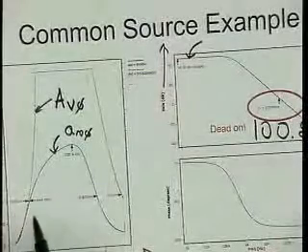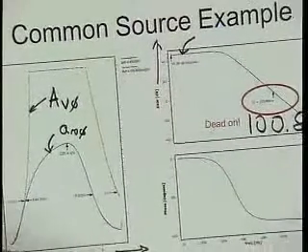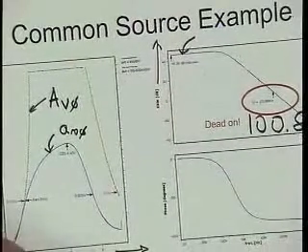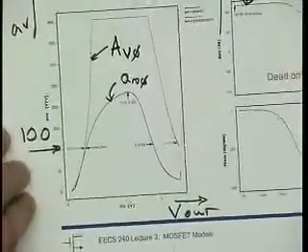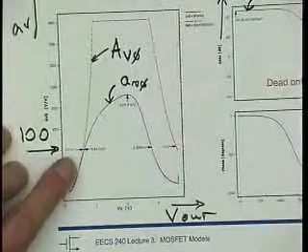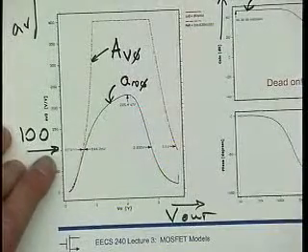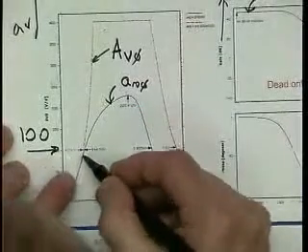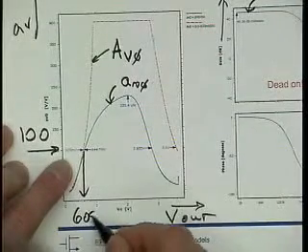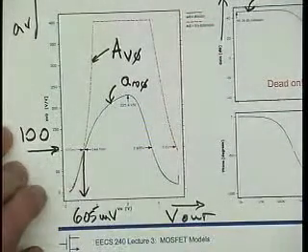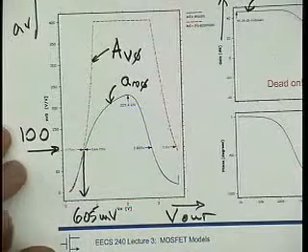But the more important stuff is here, right? Here, this line is for gain 100. This was our target, right? Actually, I didn't remember this, I actually wasn't so crazy when I spec'd a gain of 100. So what this means is we need at least 605 millivolts across our transistor.